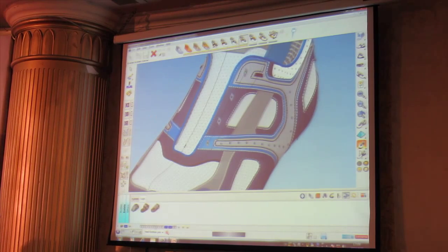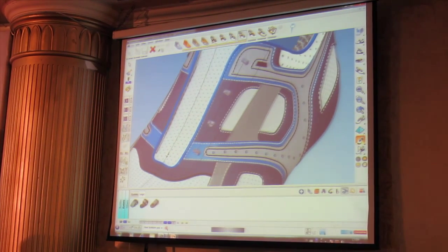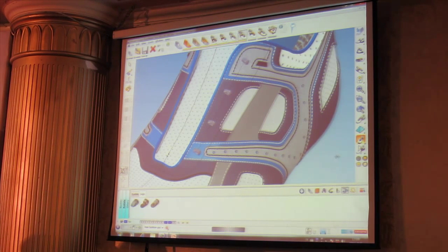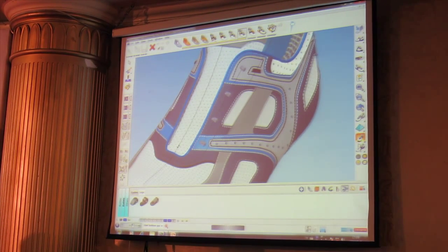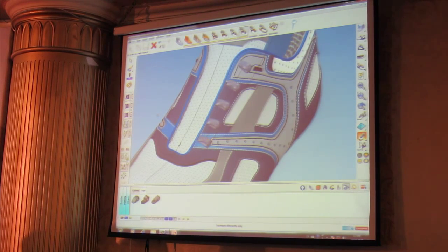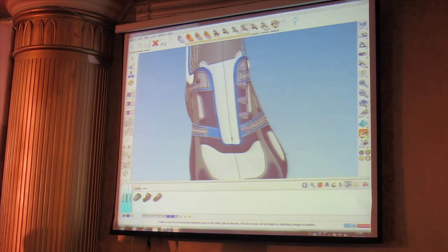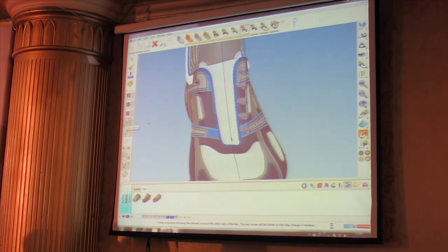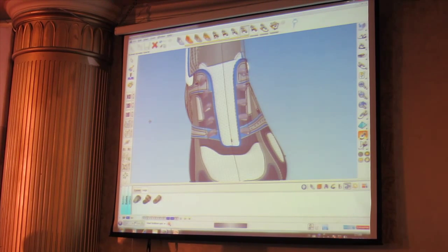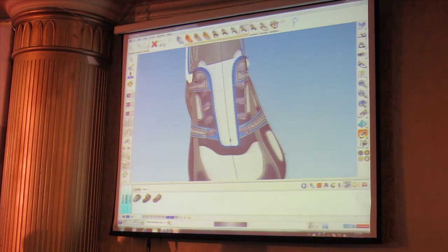Okay, so that's where I want my lugs to go. I can drag and drop designs from the library onto an existing set of accessories. I can then select the accessories, increase the separation to give me 5 lugs, and increase the size of those. If I want these on the opposite side of the design, instead of repeating that operation, I can make a linked mirror. Now with a linked mirror, if we edit one side, the other side will also edit.